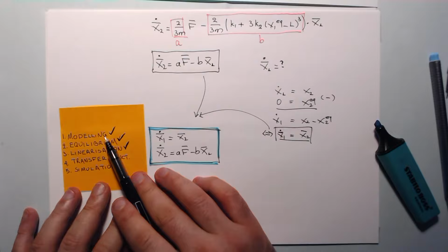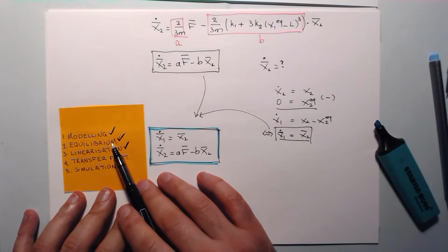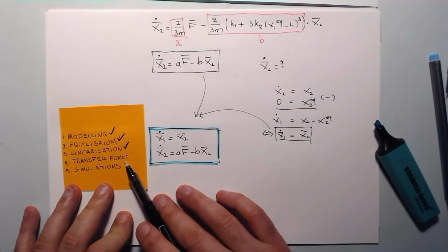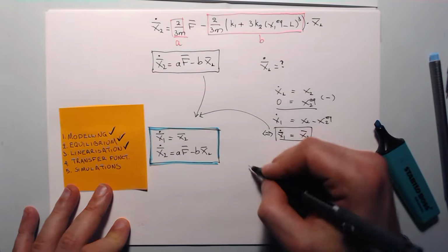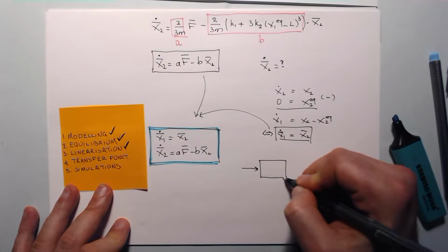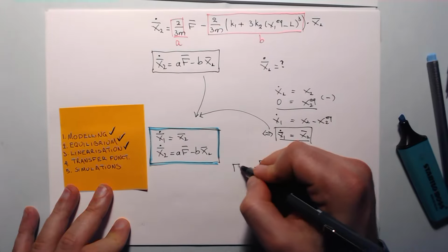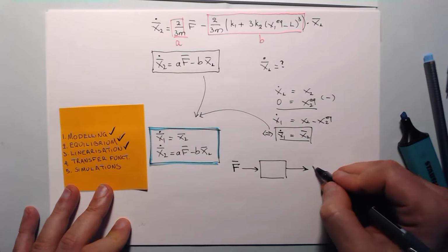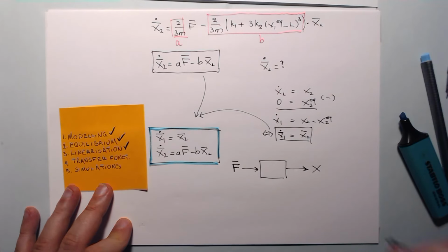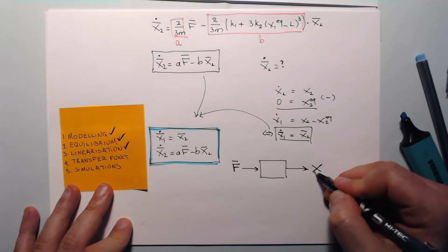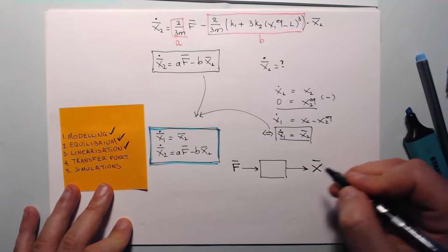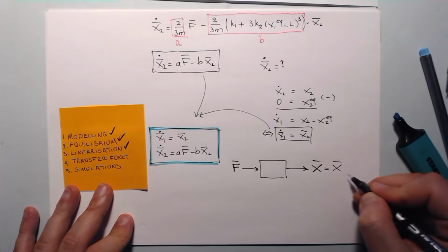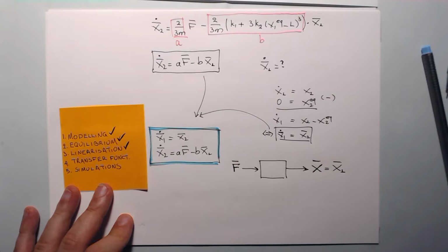And we have completed the modeling part, the determination of equilibrium points, and the linearization. Now the determination of a transfer function is absolutely trivial. What is a transfer function? It is this thing. We have a certain input, f, as a deviation variable, and we have a certain output, which is x or x1. X and x1 are the same thing, but uppercase and in the S domain, which is again a deviation variable. We can write either x bar or x1 bar. We will treat these equivalently.